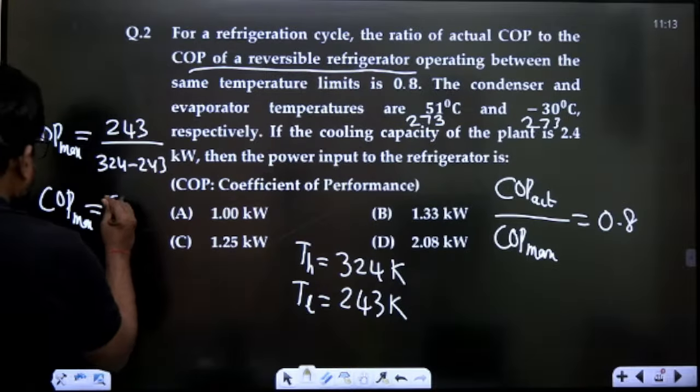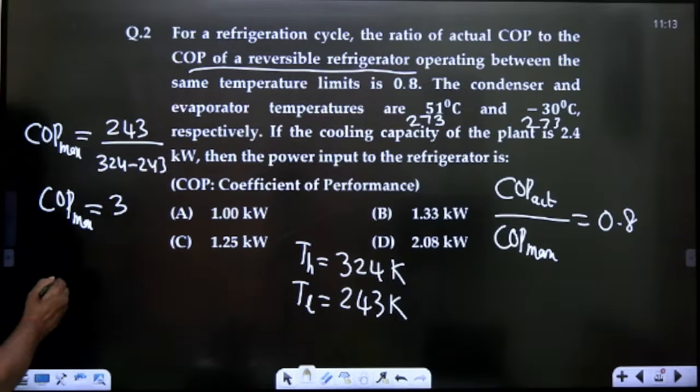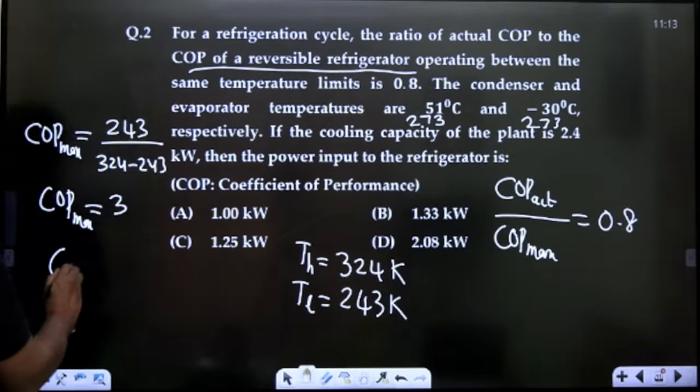I think you are getting COP as 3. So what will be the actual COP, sir? The actual COP will be equal to 0.8 times the maximum. Maximum is 3, so this comes to 2.4. Excellent. So therefore, COP is equal to 2.4. What is asked, sir? Then the power input to the refrigerator is...